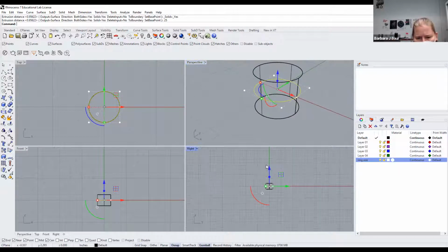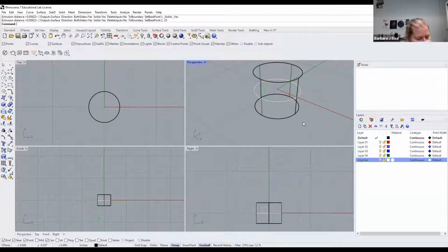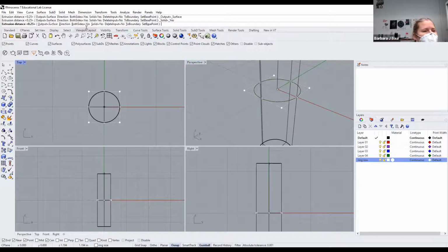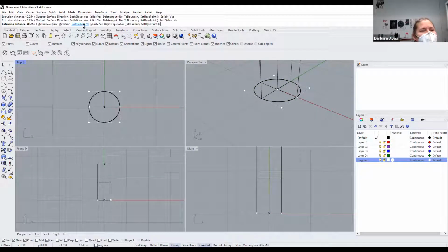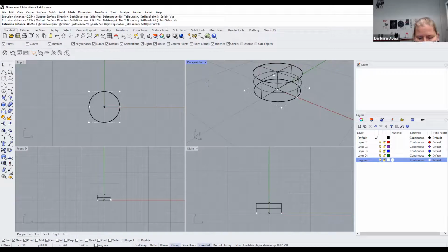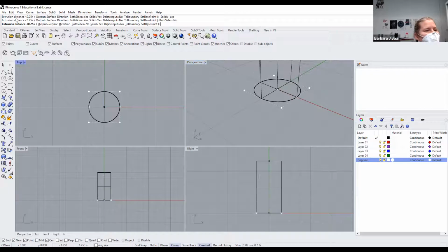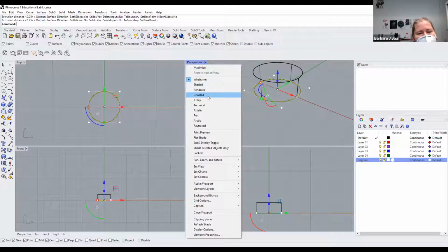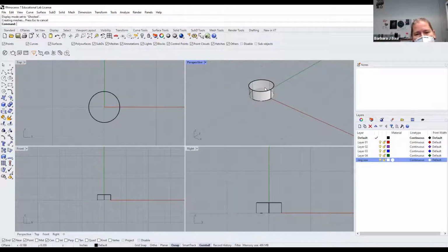That looks, oh, it went both sides. I'm going to undo. I'm going to right click to bring up the options, see how it says both sides? I only want it on one side, so I'm going to click there and change it to no. And 0.25 is already there from the last time I used the command, so I'm just going to hit enter. Over here, I'm going to make this ghosted so we can see what we've got.